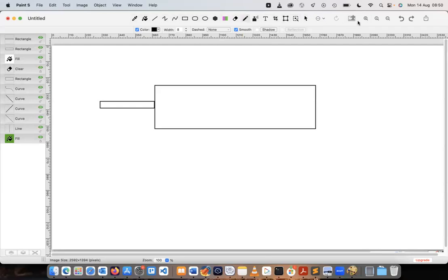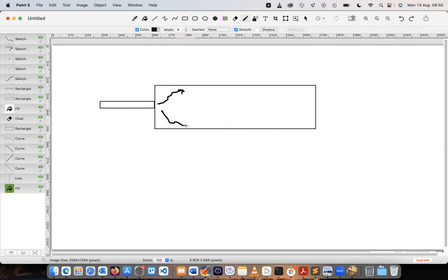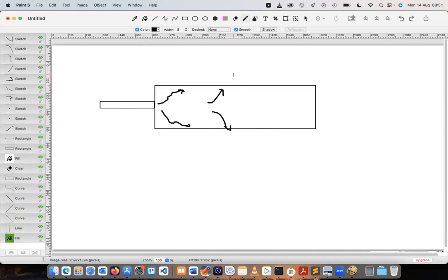Okay, so if we are expecting deposition on the wall here, then if we imagine the fluid enters here, so here's our entry pipeline, and then here is the tube that we are flowing through. We can imagine that our components are going to flow around here, and because they are being consumed on the wall, then there will be a local low concentration on the wall, right? So component A being deposited on the wall means that the local concentration of A will be low.